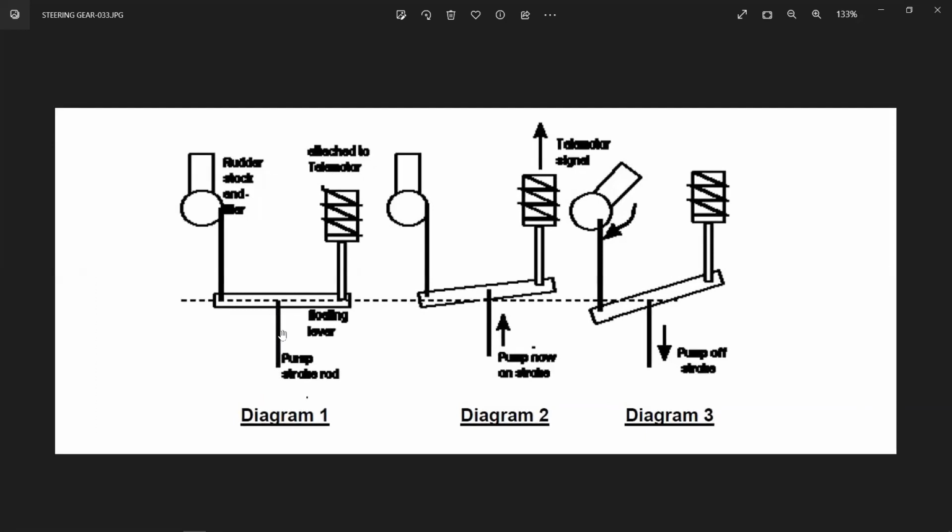If you take a Hele-Shaw pump or a radial piston pump, there will be one position where there will be no discharge. The stroke will be neutral, meaning it will not be going to either side of the discharge, because the rams or the pistons will not be generating any pressure. This pump control lever is connected to the floating ring in your Hele-Shaw pump, and moves that entire floating ring along with it.